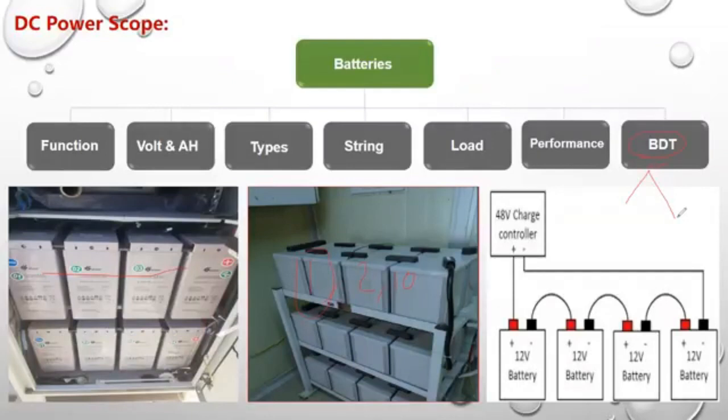I preserve the charging and discharging rates of the batteries. So if I have a site that has been a year or two and the power didn't cut off in it, when I go to do the battery discharge test, I do discharging. So in this case, I preserve the battery. The battery discharge test is done by forcing the battery to discharge, by cutting off the electrical current source coming to the site. So I cut off the breaker cable that supplies the electricity to the rectifier, so the backup batteries start to work.